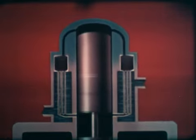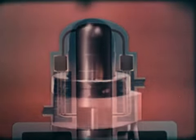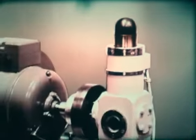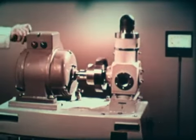It is even possible to cool the head to such an extent that the air around it is liquefied, as in the case of the famous Phillips Cryogenerator. Thus, the Stirling cycle can be used as the basis for an engine or for a refrigerator, the machine running in the same forward direction in both cases. However, if the direction of rotation is reversed, 2 other modes of operation are obtained. We will demonstrate these 4 modes of operation.